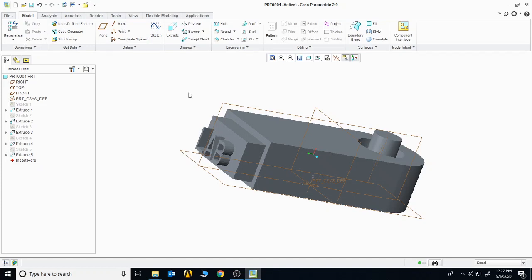That was just an example of how you can make use of all the commands that you have studied. Just try using different commands, but keep in mind that your entity will only be extruded if it is a complete closed figure. If it's not a complete closed figure, it won't get extruded.